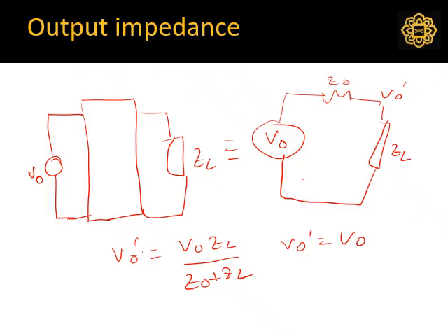So your output impedance should be as low as possible, very minute in scale, and input impedance should be very high so that you get the full voltage representation across the load. So this is the key factor you have to remember. Okay, let's move forward.